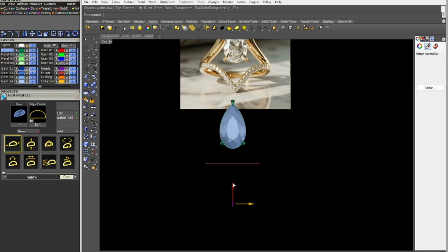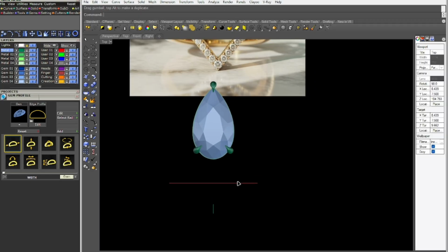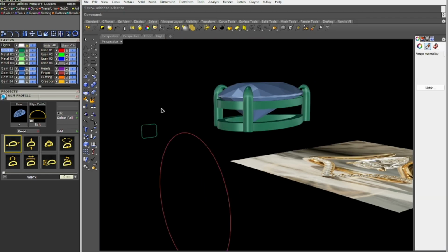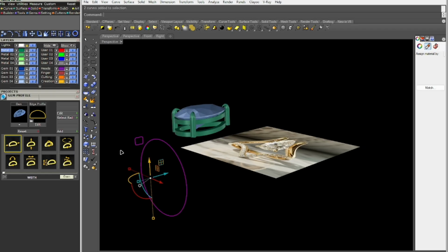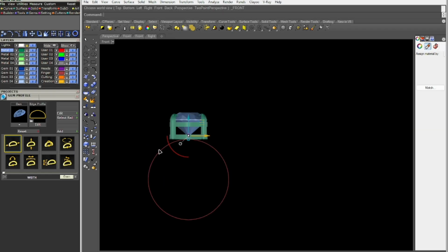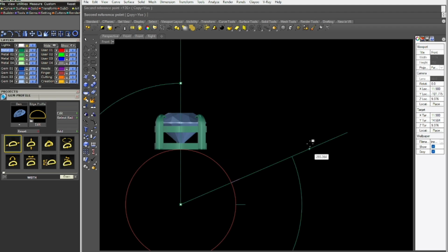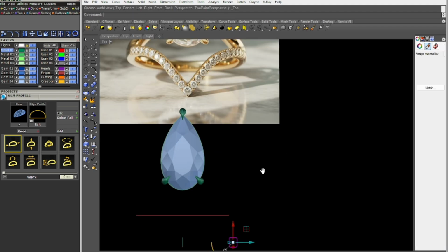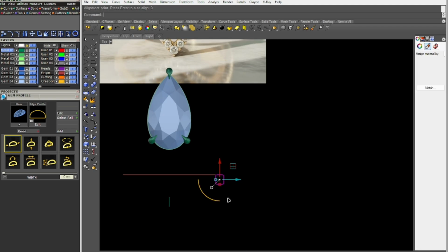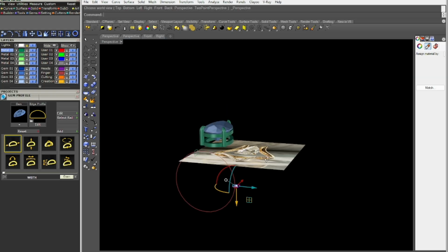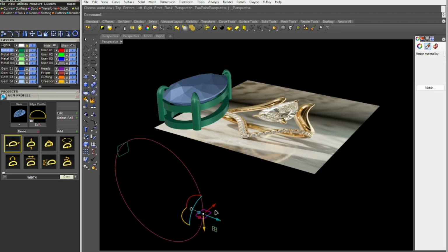Let's do sweep 1. Before that, we need to copy this cross section at multiple places so we can connect the cross sections to each other. In a similar way you can also create a copy.